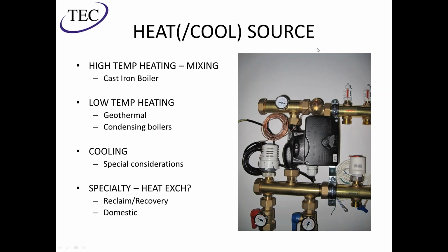Touching on the heating and cooling source, if you're using a high temp boiler that's existing, or steam, for example, you may need a heat exchanger, or you may need a mixing valve. Over here on the right, Howe and other manufacturers as well have a bolt-on mixing system. So this has a little supply pump, and then a thermostatic mixing head, checking the temperature and turning the pump on automatically based on whatever control you attach to it.